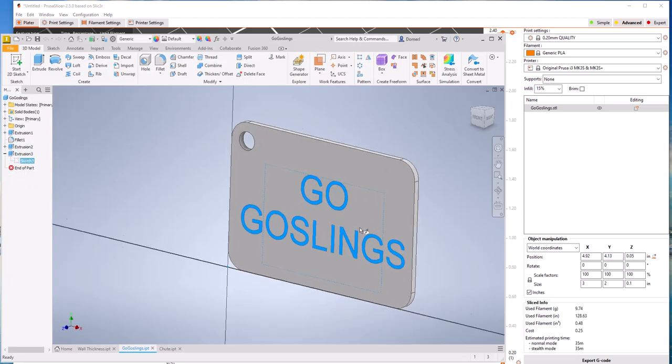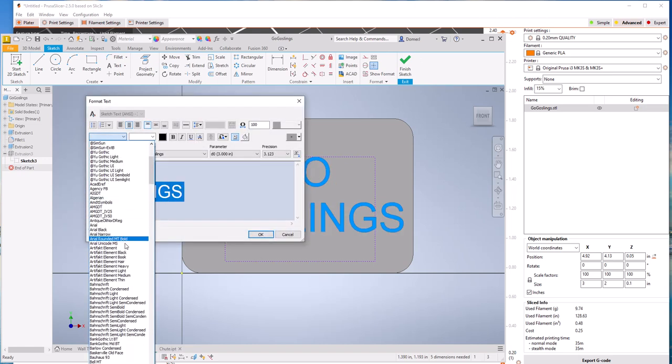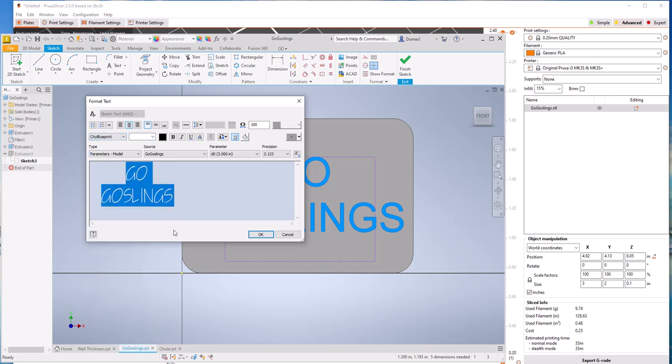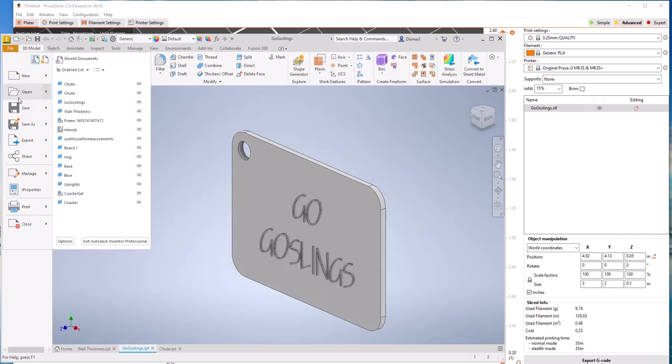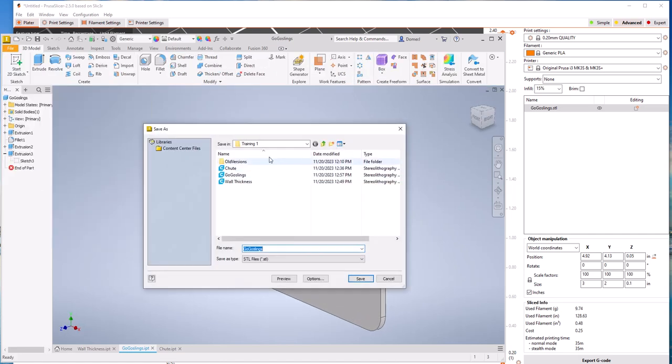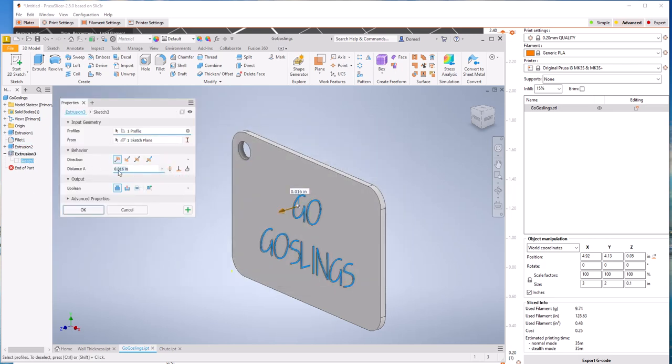Let's change our font on this to something like City Blueprint. Finish. Export that file. Actually, I'm going to make it go farther out too. So I went 16 thou was about 2 layers. About 8 thou is a layer-ish. So for every 8 thou, it's going to put another layer roughly in Prusa at 0.2 quality. So it's something to think about.